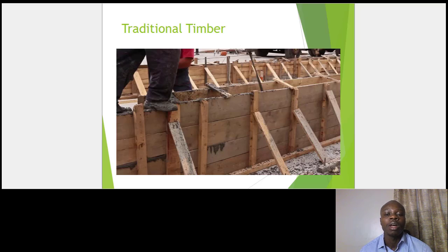For what has been presented, for instance, it is simply formwork, the traditional timber formwork. Of course, formwork is of different types. There are those that will use plastic formwork, steel formwork, depending on what is available and depending on the kind of final finish of the concrete that you'll need. That is going to make you decide on which type of formwork to use.